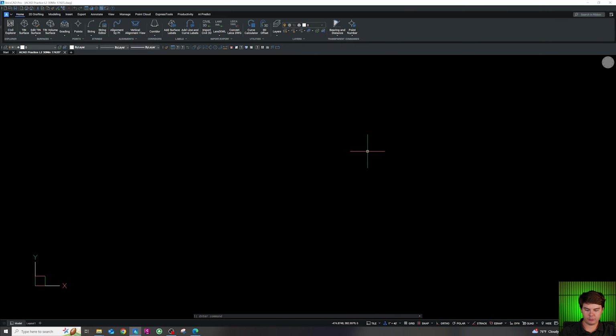I'm going to start off by drawing the property lines, and to do this you click a line and press at, and then whatever distance your line is, mine's 463.44 feet, less than symbol, and then the bounds, so south 0 degrees, 49 minutes, and 1 second west. Now we'll just go around and proceed with the same process.